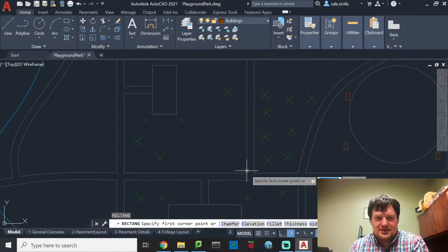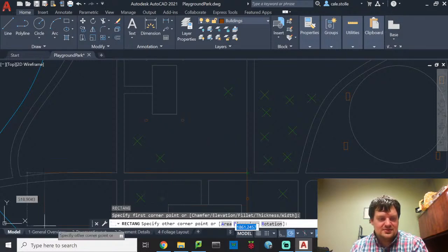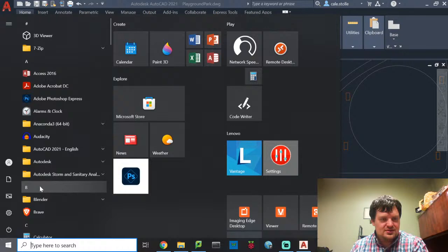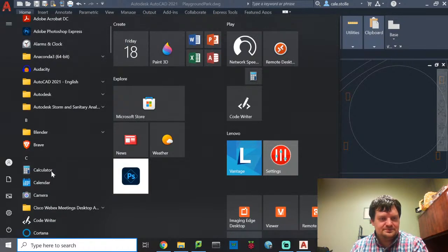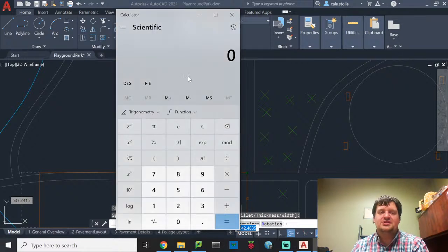Just terrible. I want my restroom to be, let's see, 16 feet by... let's do some math, calculator. I draw where 1 unit is equal to 1 inch. I like to do that. For most of you, you drew with 1 foot equals 1 inch. If you scale your drawing up by 12, you'll get the exact same thing. I just like to do that because it makes units a lot easier.